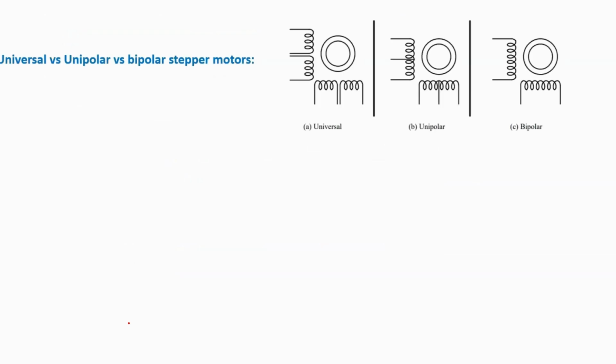So till now we discussed the unipolar stepper motor, which was a 4-phase motor. Actually, we also call it a 4-phase motor. There are actually 3 types of stepper motors commonly used. This was the unipolar motor we discussed till now, which has 6 terminals. These are 4 terminals A, B, C and D, whereas these 2 middle terminals are center tapped, which are usually connected with 5 volt. So whenever we find any stepper motor with 6 leads at the terminals, then it is actually the unipolar stepper motor.